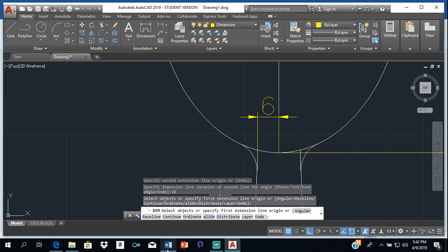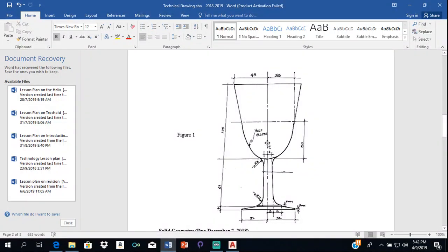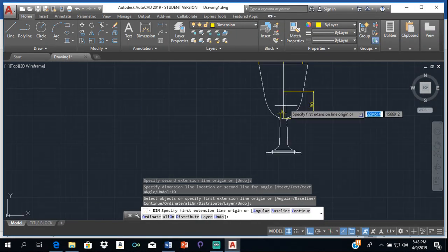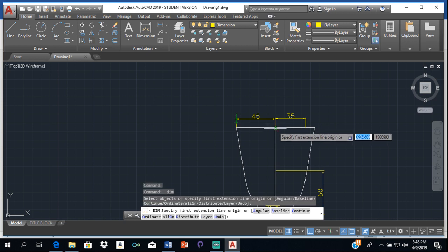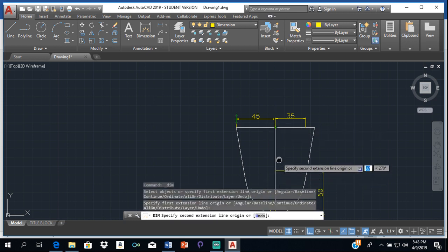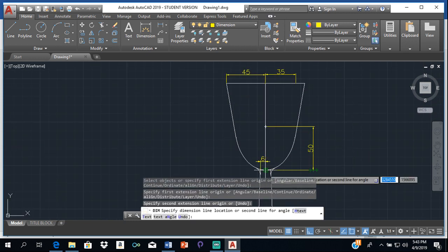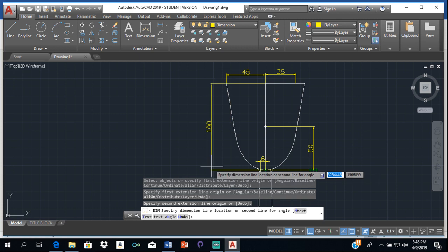In the drawing it's dimensioned on this side, but there's no problem if you do it on this side. Alright, so with that done now, we are going to dimension. We can put in the 100 right here. So let's do that. Dimension, we click on dimension, click from here to down here, and bring this out by 55.